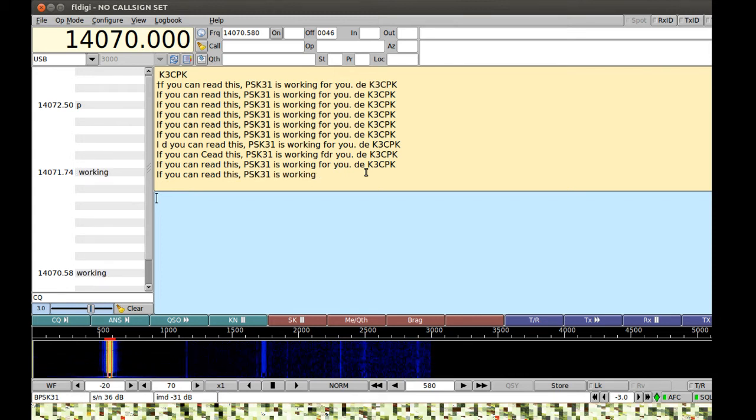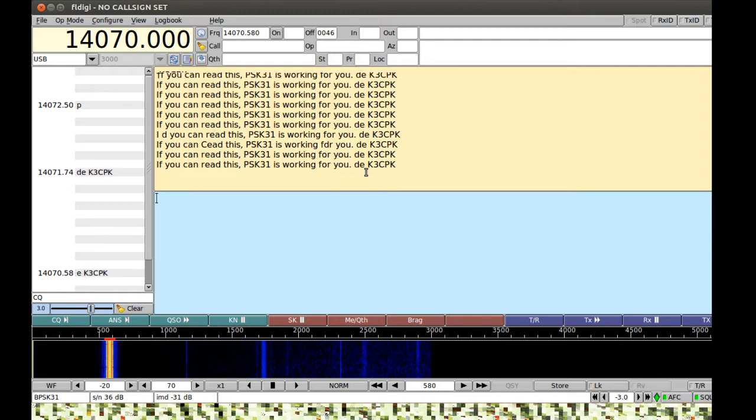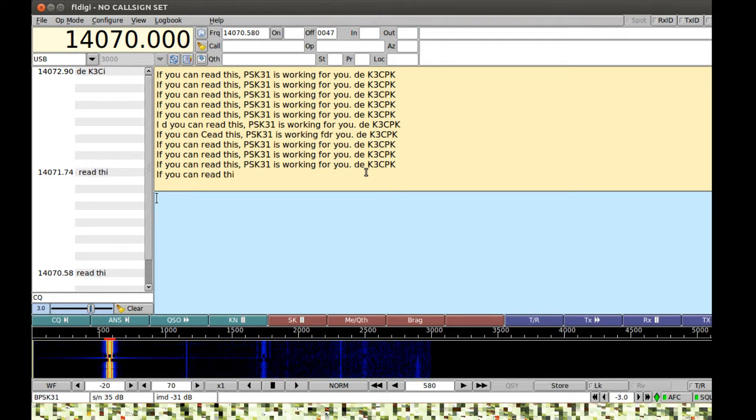So you were also having trouble? Oh, you're the one with the really small writing on the screen. Yes, I got some of the AFSK 1200 bursts and not all. And I'm not sure if I have the right op mode selected here. Is PSK 31 the same thing as BPSK 31? Yep, BPSK 31 is the correct one. And then there's also QPSK, however, QPSK should not decode it for you.